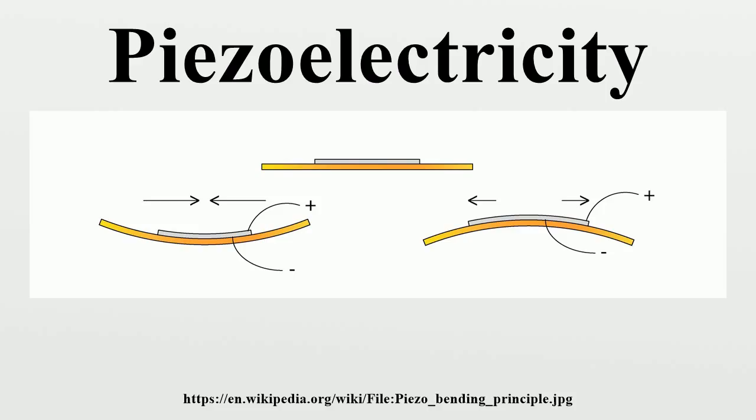That is why S and T appear to have the vector form of 6 components. Consequently, s appears to be a 6 by 6 matrix instead of a rank 4 tensor. Such a relabeled notation is often called Voigt notation.